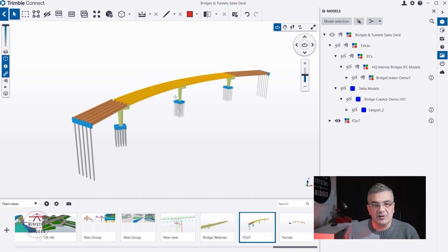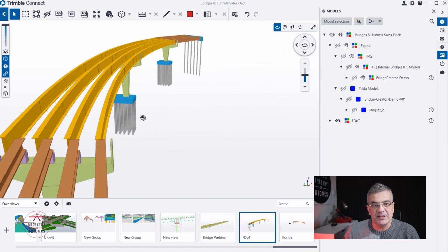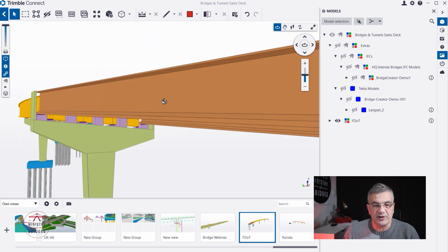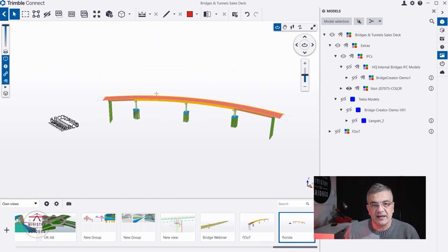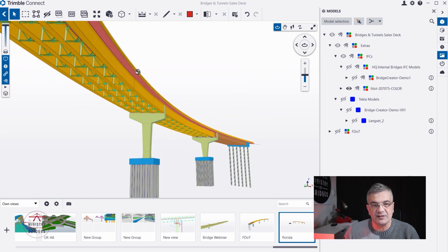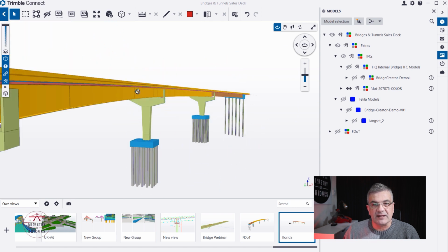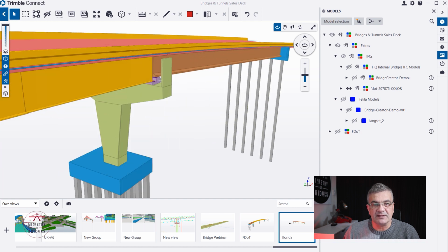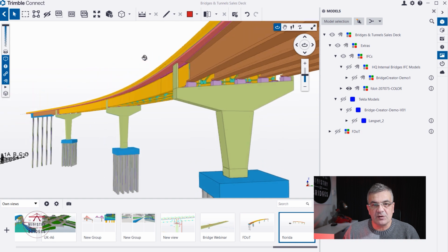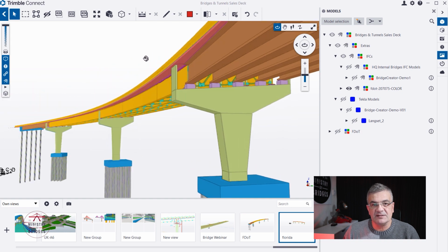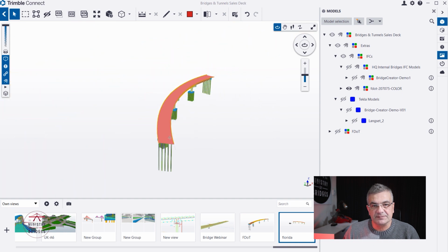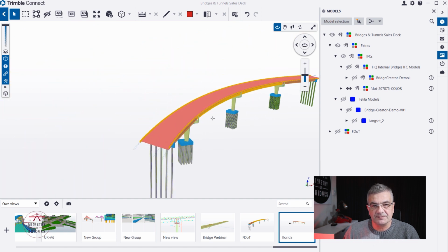One more example: you can place beams or poly beams constrained to those lines, to those points. The deck, the superstructure of this bridge, was all built with Bridge Creator, and then the bracing was applied after, obviously. So here, precast concrete beams and steel poly beams, the girders.